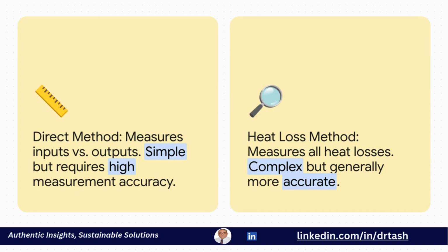And here's why. Think about it. If your measurement is off by 1% on a tiny little heat loss, it's not a big deal. But a 1% error on your entire fuel input, whoa, that's a massive problem. So yeah, your choice depends on what gear you have, but if you want a really surgical view of what's happening, the heat loss method is often the way to go.